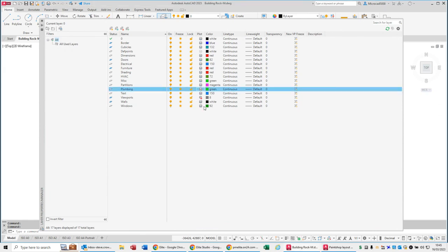Okay, so turn back on again. I quite often get questions from customers saying, why is the stuff not printing? So I'll say, what layer is it on? And they'll say, oh, it's set to no plot. So remove the red mark and away you go.